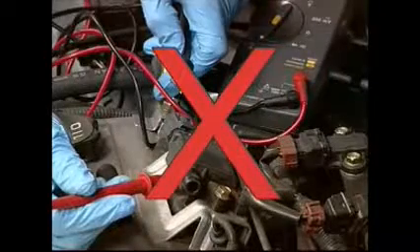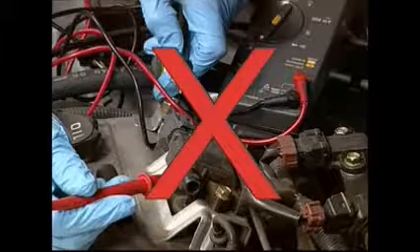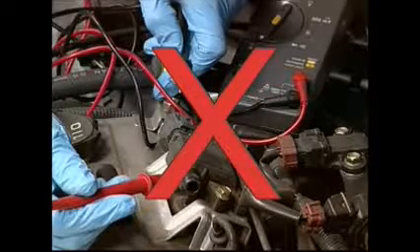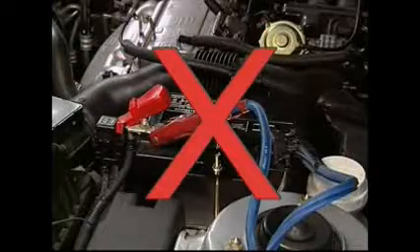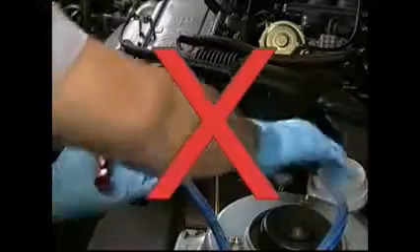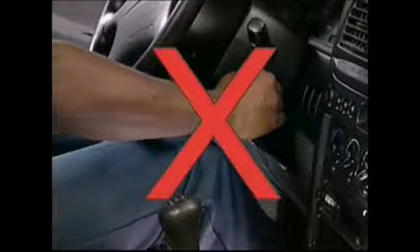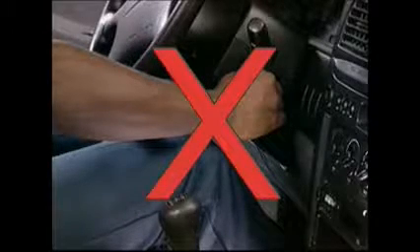Never attempt a current measurement where the voltage is above 600 volts. If the meter fuse blows, you can be injured and the meter will be damaged. Never attempt to do a current draw test on a lead-acid battery that has recently been recharged. And never crank the engine or operate accessories that draw more than 10 amps when doing the test, or the fuse may blow and the meter can be damaged.